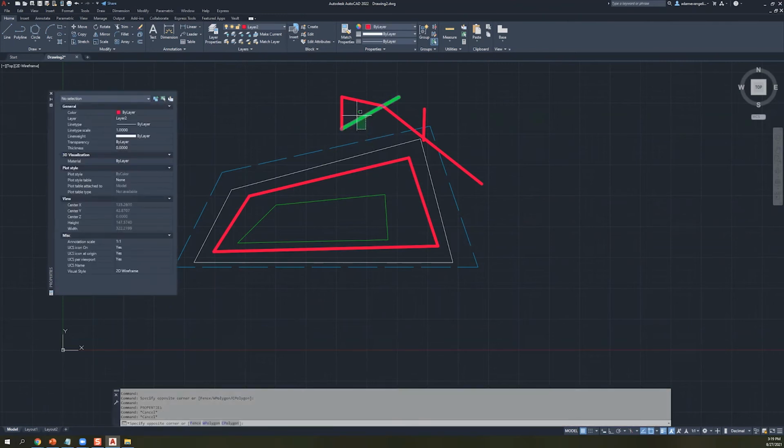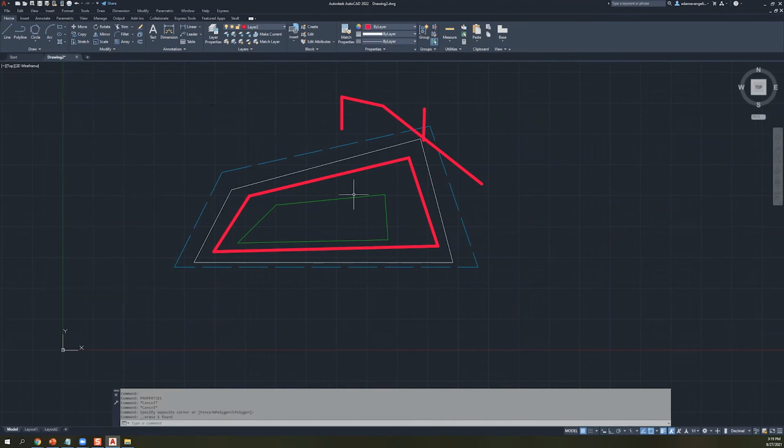You might be wondering, okay Adam, that's great and all, but what if I just wrote a piece of geometry on the wrong line or on the wrong layer or something like that? Could I push it to a different layer? Answer is absolutely. Just go ahead and select the objects that you're concerned about, go to your pull down over here, and then you can choose it and push it to a different layer like so.